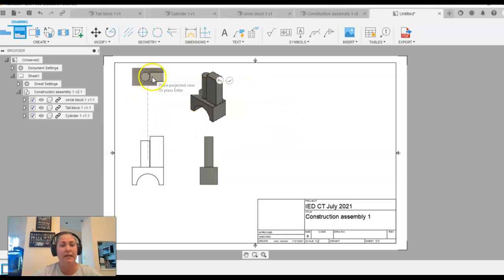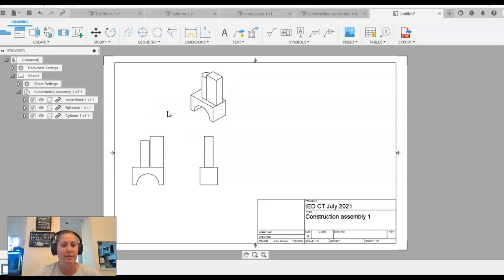And now I want to move it anywhere. I don't need my top view for what we're doing. You could put it, but I don't need it. I'm going to hit escape on my keyboard. That makes it stay. I'm going to double click the isometric view. It's always isometric top, front, side. Since we're doing exploded, I'm skipping that top.